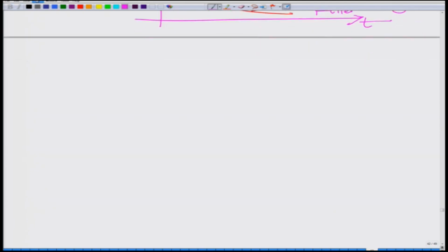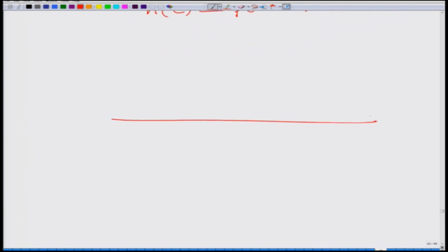Now h tau, we have h tau equals Pt minus tau. Now how do we get h tau from Pt? First we have to flip. So step 1, we have to flip. So this is P of minus t. So the first step to construct the impulse response of the optimal receive filter which maximizes SNR is to flip Pt to get P of minus t, then you advance by capital T.